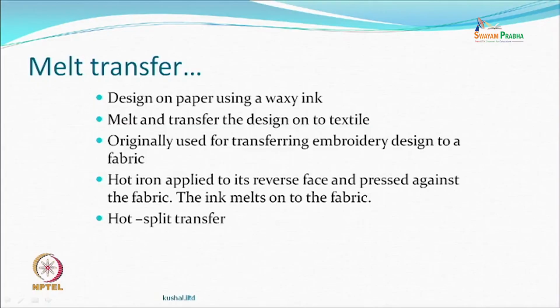Of course, you will have to worry when you wash it, when you rub it, so abrasion resistance and all those kind of things are going to come into play. But if you are looking at fashion, this is it. You can work around. Sometimes it's called the hot split transfer also. So it's a split. You are splitting the material from that portion and getting it onto the textile, because sometimes maybe a film which is the same color, but you are splitting it, and the design can come just like that. Only a portion, and somewhere the material has gone out and gone onto the textile. And you see that, so you see blank on the thing.